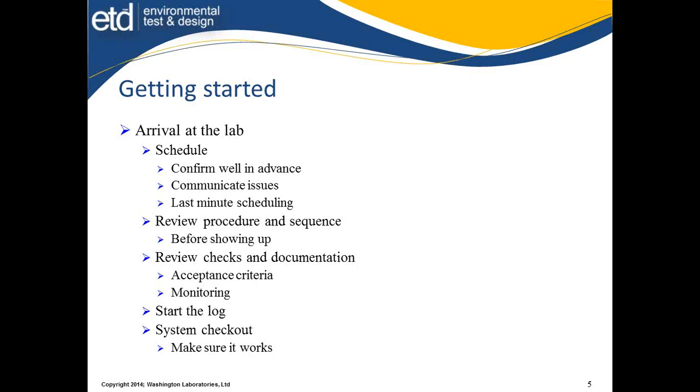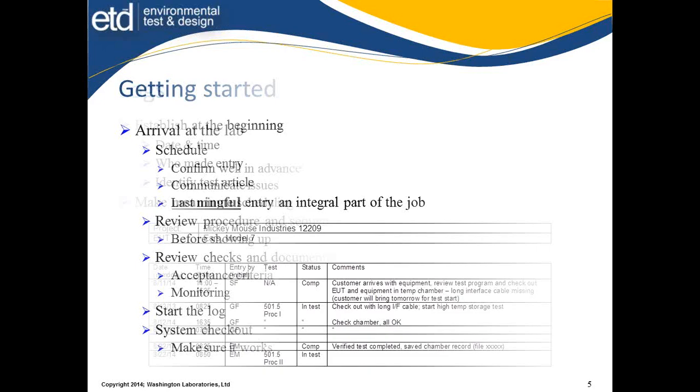Don't go doing storage tests until you know it's working. Because if at the end of the storage test it's not working, did it happen during the test, or was it an infant mortality that happened before you ever got going? You shouldn't start tests until you know you've got a functioning unit that complies with all the functional testing needed.